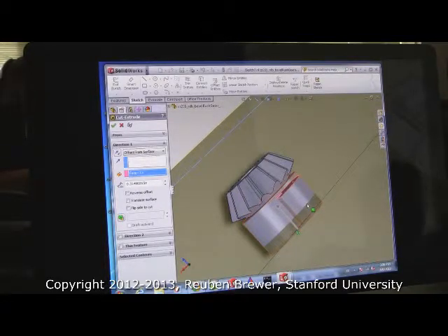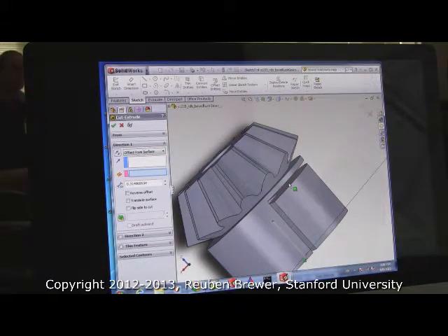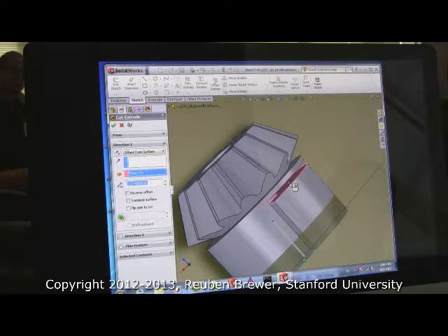Wait, could you go over that last bit again? Yeah. I have the extrude option, so now I'm just choosing offset from surface, and then select this surface right here, and then type in 8 millimeters. So this is a super helpful one, because it lets us use other geometry to define the depth. Everybody good? Which surface are we going up to? This one right here.